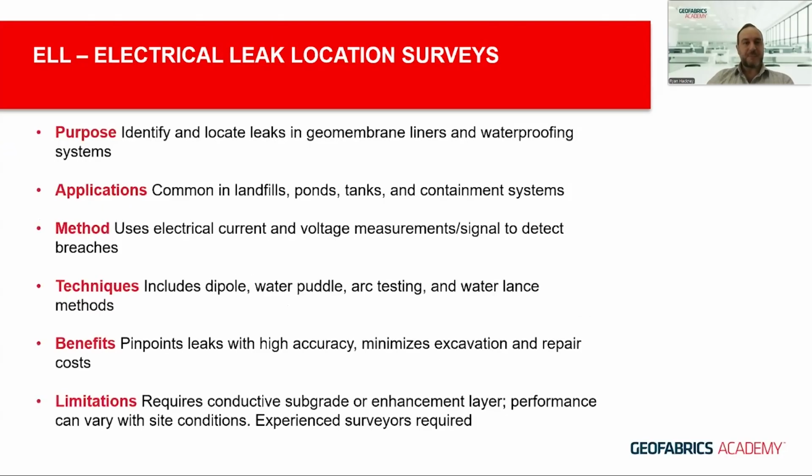So the purpose of a leak location survey is primarily to identify and locate leaks in geomembrane liners and waterproofing systems. As we've mentioned previously, the applications include landfills, ponds, tanks, and containment systems. The method itself uses an electrical current and voltage measurements, or the signal of those, to detect breaches in the lining system.